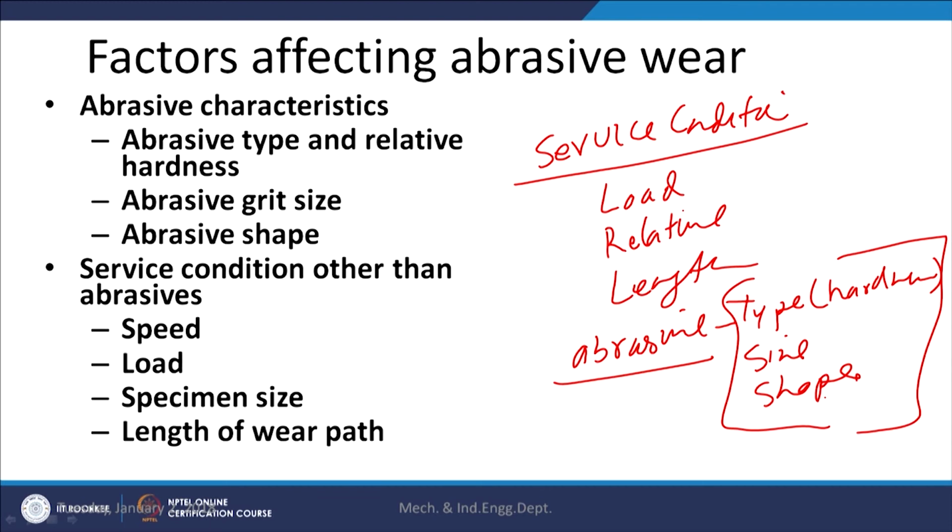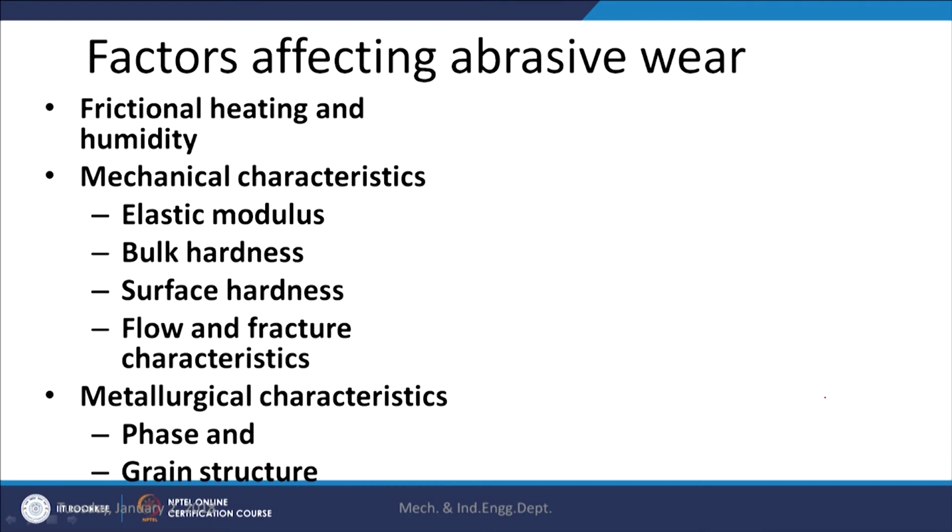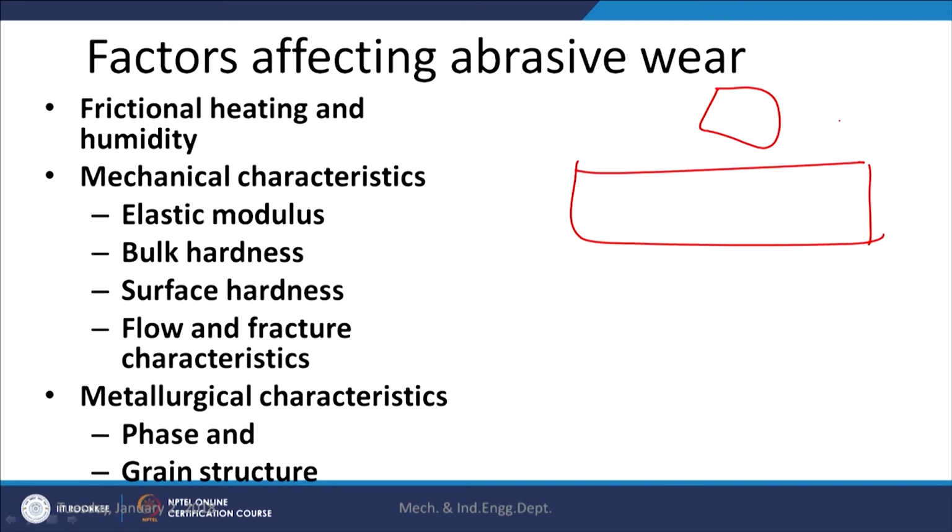Apart from this, there are other material related factors and surface condition related factors, like whether the abrasive particles are interacting with the surface under ambient condition or at a high temperature, in the dry condition or in the humid condition. So, these factors will be affecting the abrasive wear.